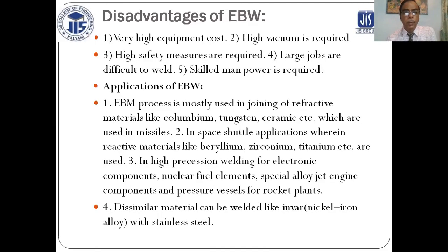Disadvantages of electron beam welding: very high equipment cost, high vacuum is required, high safety measures are required, large shapes are difficult to weld, and skilled manpower is required. Application of electron beam welding.